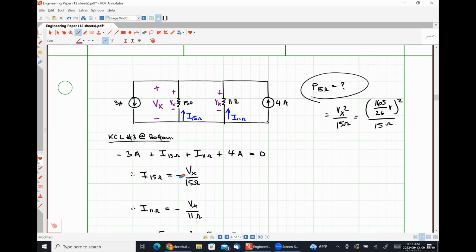So great question. Christina just asked, what happens if we apply Kirchhoff's voltage law to a system like this? The short answer is that regardless of what loop we apply, so let's go around this loop right here, we would see the negative polarity terminal of Vx first, then we have a short circuit, then we see the positive polarity terminal of Vx, then we hit that other short circuit, and the sum is equal to 0, which means negative Vx plus positive Vx is equal to 0. Of course it is. So that effectively means everything has the same voltage, because regardless of what loop or path we choose, we're going to get the negative voltage plus the positive voltage equal to 0.